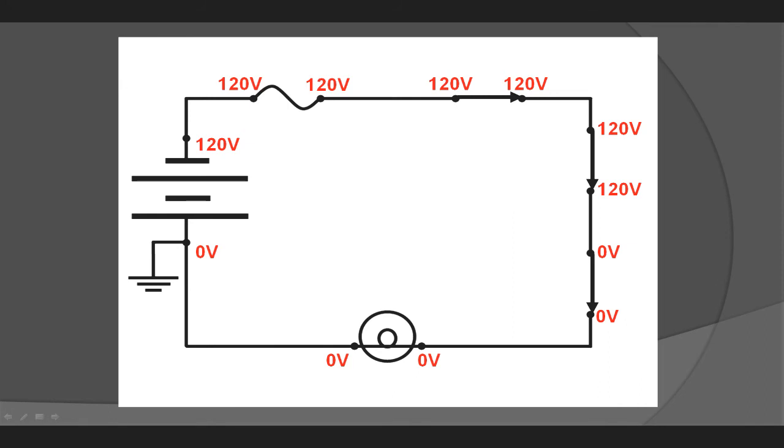If you said the fault is in the wire between the second and third switch, then you are correct. The last point of potential is directly downstream of the second switch, so the open must be in the downstream wire. Now consider this one. Given these readings, where do you believe the fault lies? In this circuit, there's an open in the first control switch itself. Again, the open is between the last point of potential and the point of no potential.